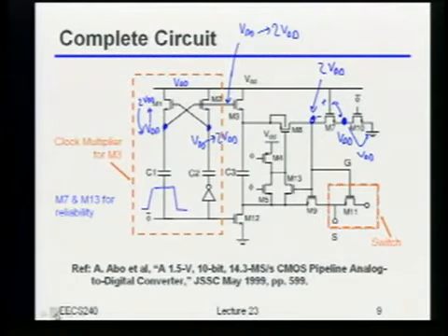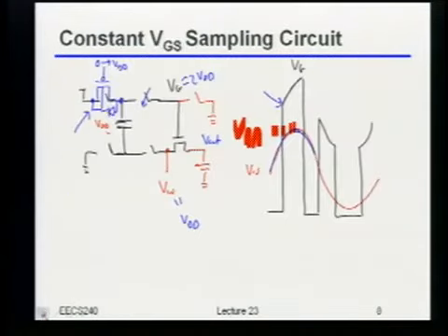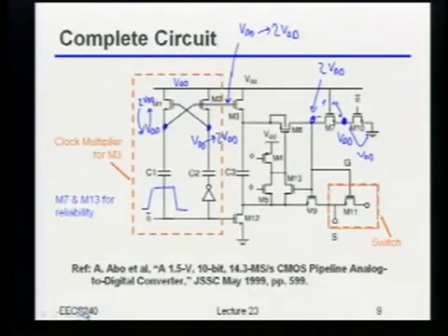I point this out because, as I mentioned, there are going to be a lot of times where you want to use voltages that are larger than what your process can nominally handle. It turns out this simple trick lets you get away with up to about twice the nominal process voltage without too much muss and fuss. You can, of course, do the same thing with the PMOS devices as well. I'd encourage you to take a look at these 4 or 5 transistors that are added here and make sure you understand what's going on. Conceptually, all they're trying to implement is exactly this thing. They're just doing it in a way that makes sure nothing blows up and things don't turn on when you didn't want them to. Does this make sense to everybody?